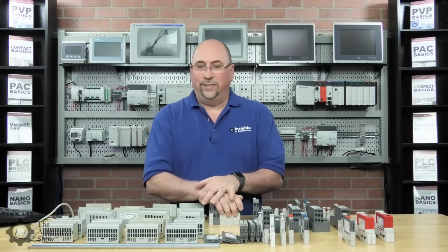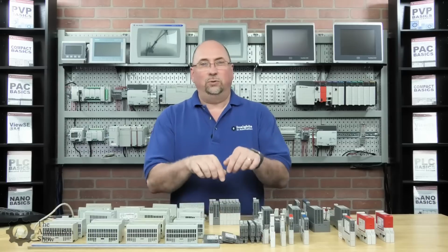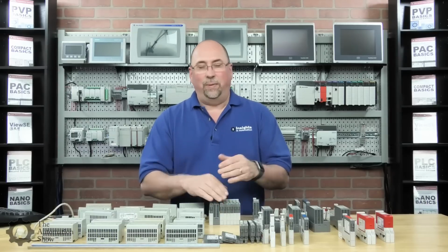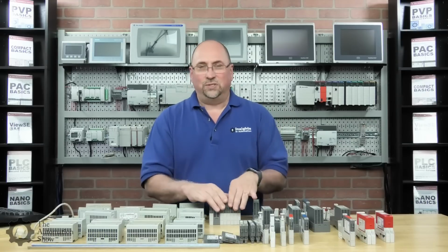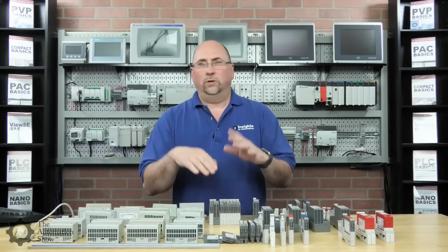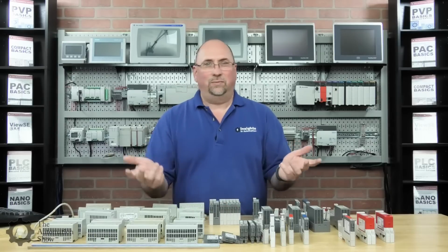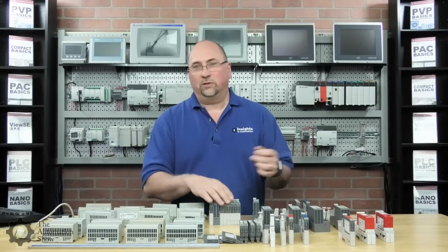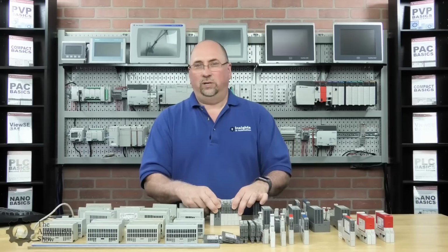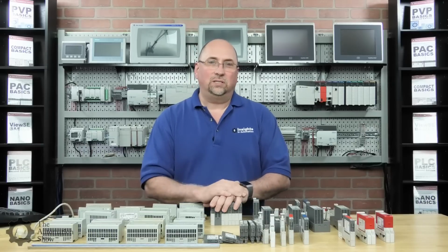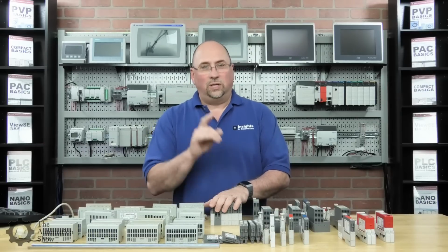And it kind of baffles me. I don't understand why this is. I don't know if it has anything to do with the DeviceNet bus that really makes up the backplane of the point I/O. But you can find there's a tech note over at Rockwell that covers all this. But I've seen it firsthand with point I/O. If you're doing a redundancy system, especially, because a lot of times with redundancy, right? That's why you have two controllers. You can update one while the other one controls the system. But here's the thing. Typically, you're not going to use point I/O in redundancy systems because typically in redundancy systems, last state is important. So keep that in mind.